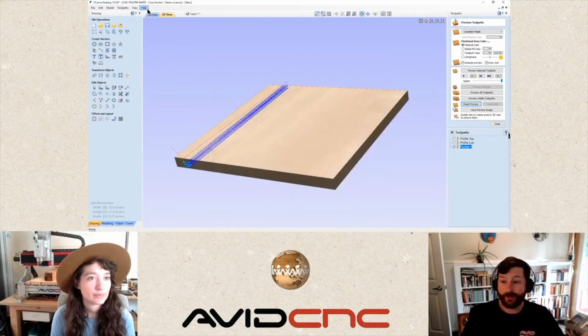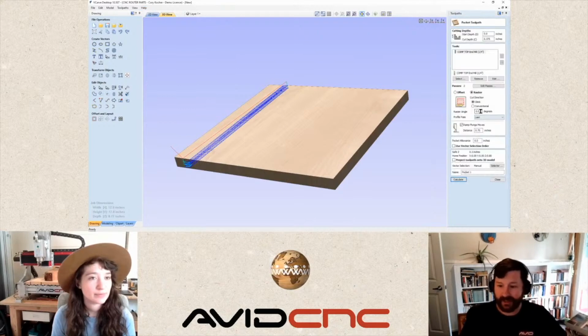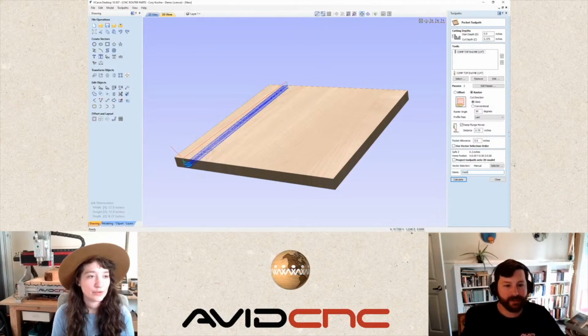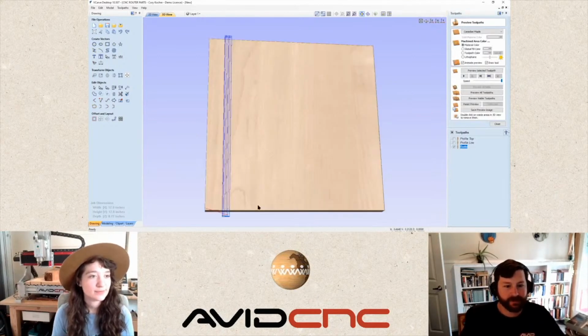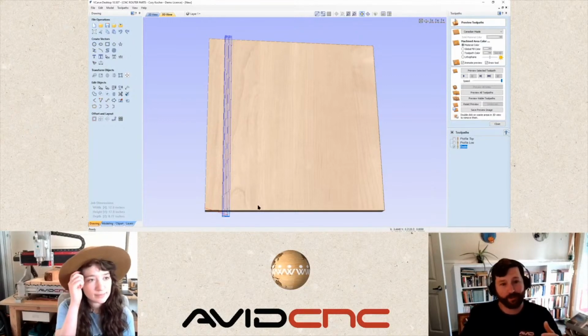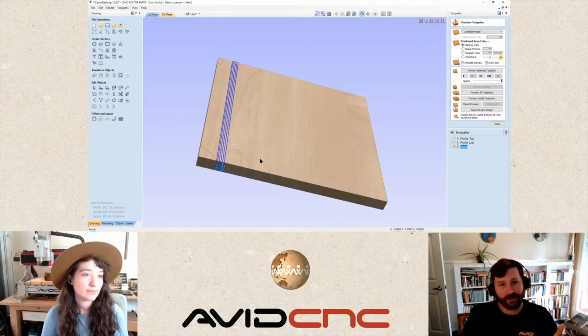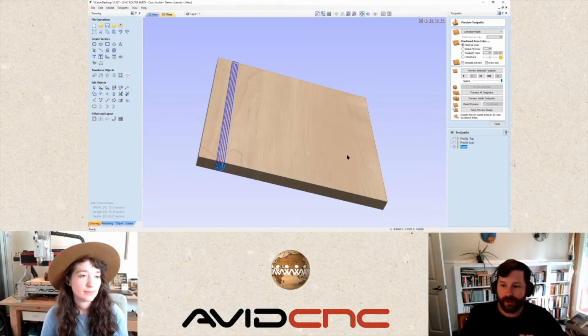And this is one click away from perfection. So if we go back into this and we just change our raster angle to 90 degrees and we recalculate this dado, now there's a much cleaner toolpath, and that's going to be efficient, and we're going to get to use that downcut part of our tool on our top veneer because our depth of cut is 0.3, and then we're going to be taking that last 0.075 out with the upcut part of our tool.